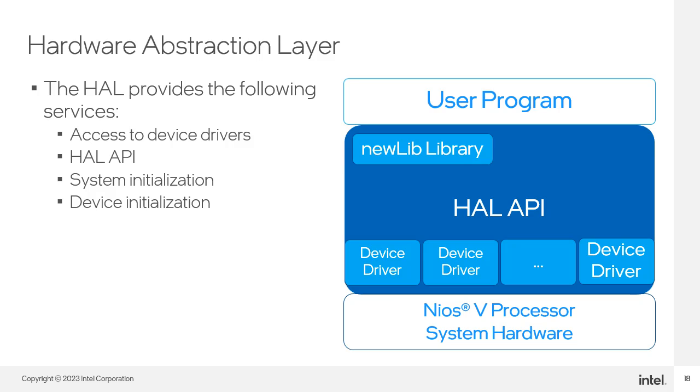The HAL Peripheral Services provides your application with a set of services, typically relying on the presence of a hardware peripheral to support the services. By design, the HAL attempts to enable as many services as possible based on the peripherals present in the system hardware, and provides control over the initialization process, system optimization, and configuration. The changes made to the hardware configuration propagate to the HAL device configuration to avoid any inconsistencies in the IP.